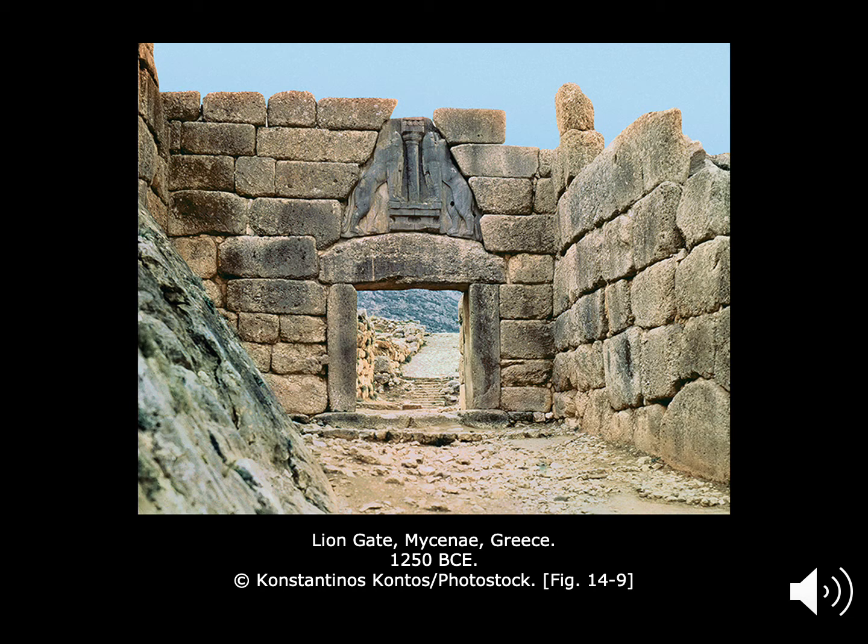Walls may employ one of two basic structural systems. The shell system involves one basic material providing both structural support and outside covering, often solid all the way through. The skeletal and skin system consists of a basic interior frame that supports a fragile outer covering. Walls of the lower floors must also support the weight of the upper floors.